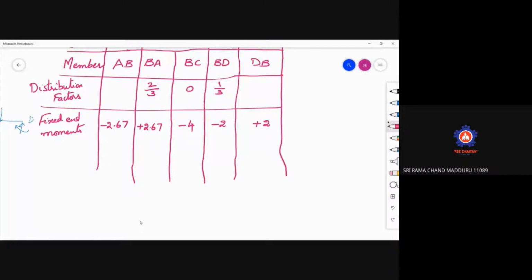So here a slight difference is there from the previous problems. In the previous problems, we used to consider only a beam like this. So whatever the overhanging moment is there, we equated that to this support. For example, if you got -22.5 kN as the overhanging moment at this support, for the joint condition we made it +22.5 kN. But now coming to here, another member is also there. Three members are meeting.